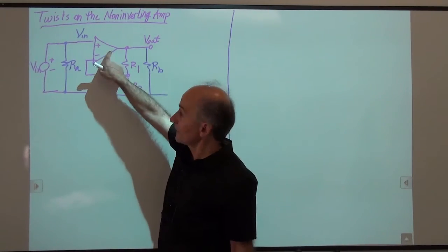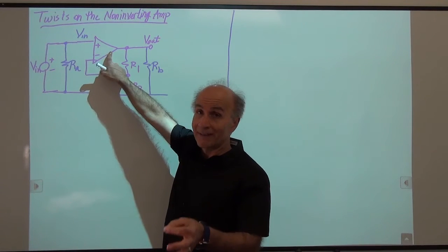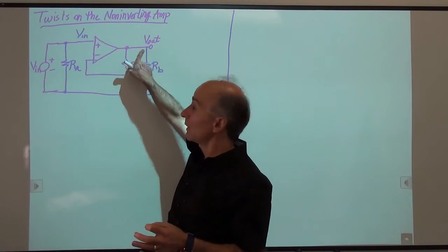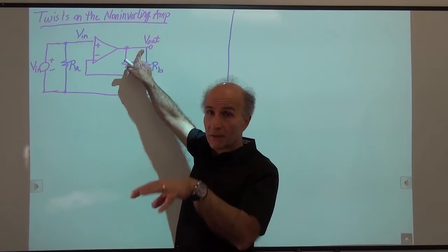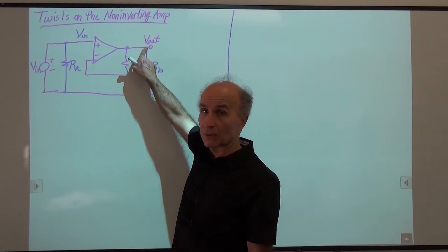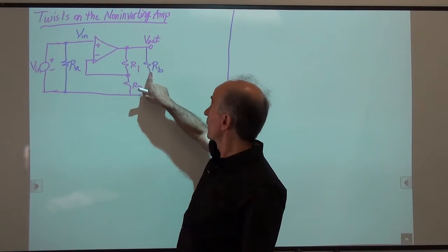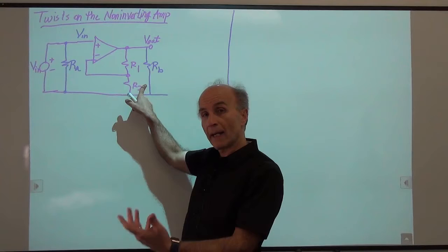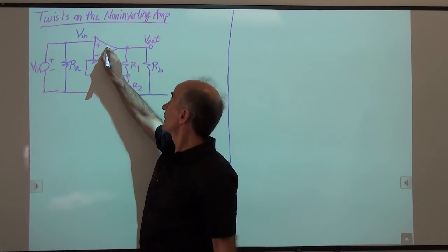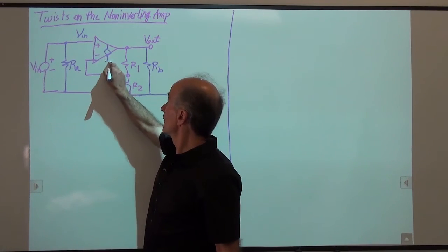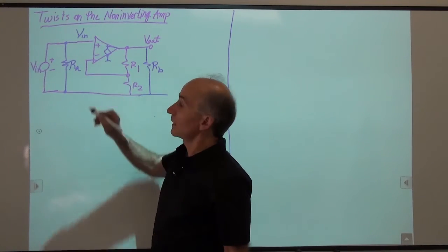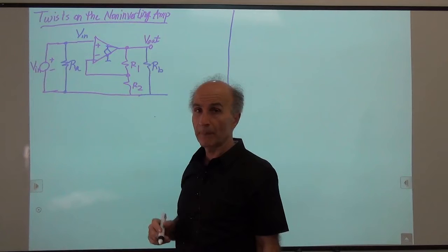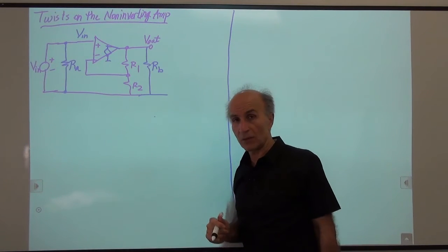And we know that inside this op-amp, there is an ideal voltage source. So as long as an ideal voltage source is connected to this node, it wants to impose its own voltage at this node. It does not matter whether RB is 1 mega ohm, 1 kilo ohm, or 1 ohm, as long as that dependent source is here and it's an ideal voltage source, RB does not change the results. So again, the results do not change.